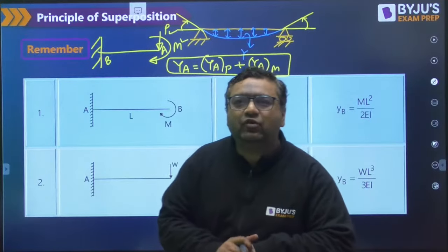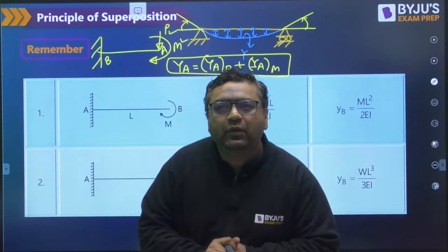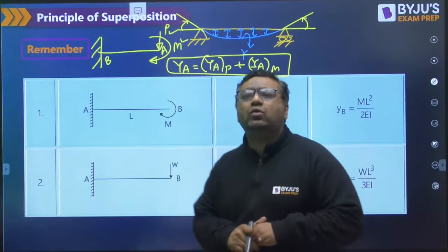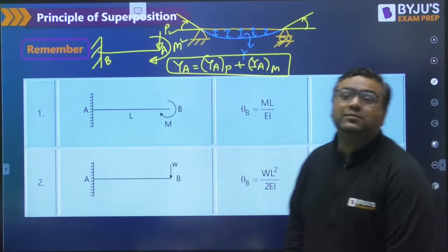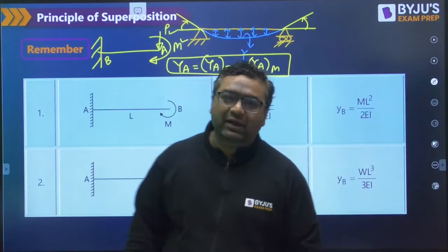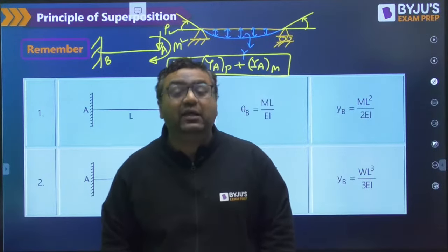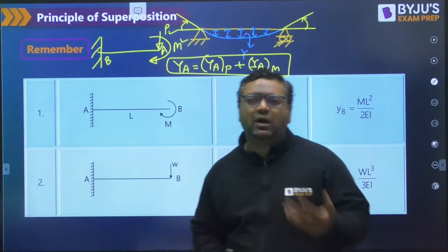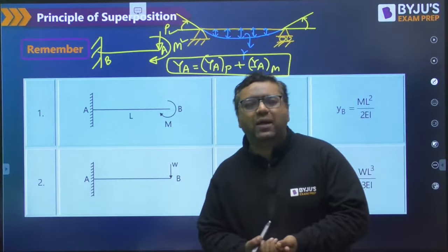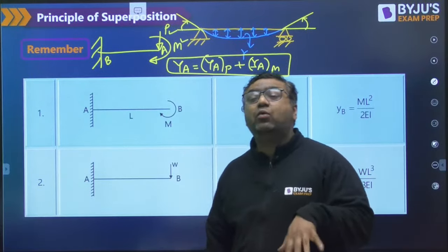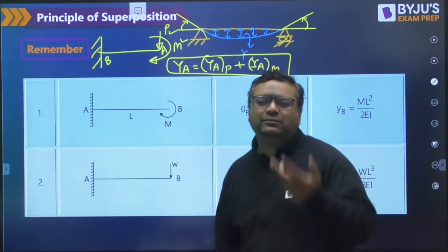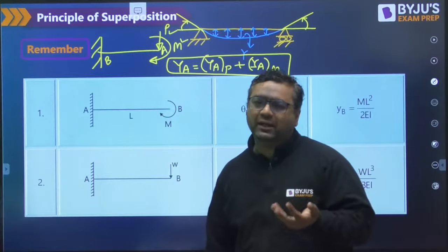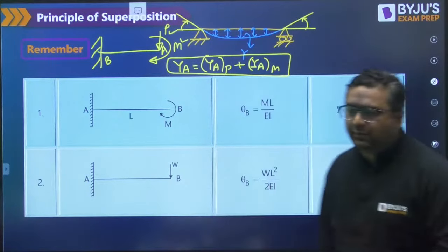Regarding the methods for non-prismatic beams, we have the Mohr method. All the other methods, like double integration and Macaulay, are applicable to prismatic beams. And when we talk about Mohr's method, both the conjugate beam and moment area methods are applicable to non-prismatic beams.